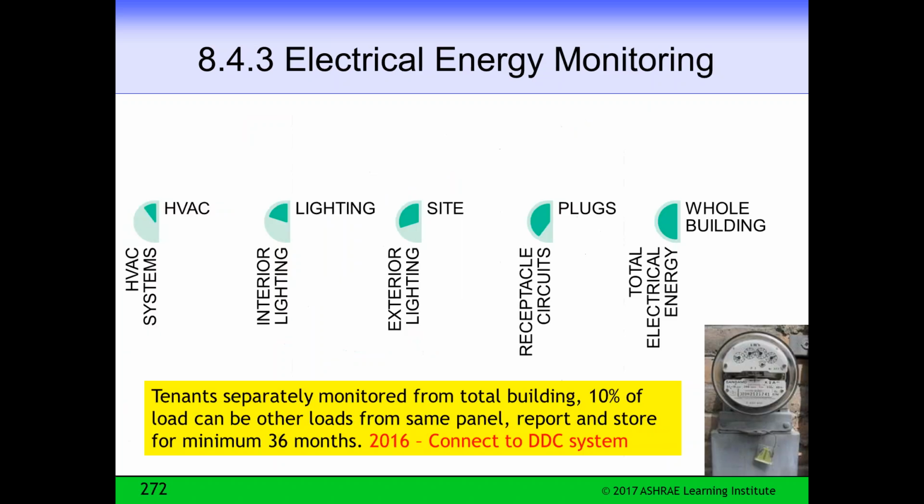All right. Electric energy monitoring. Now this is something that's new. That's new in 2013, and in 2016 we added the requirement to connect it to the DDC system. But this to me is a bigger impact than the outlets, because this changes the way you normally would wire a system for the electrician. Now the electrician is probably going to have to add a panel, and that's probably going to cost more money,